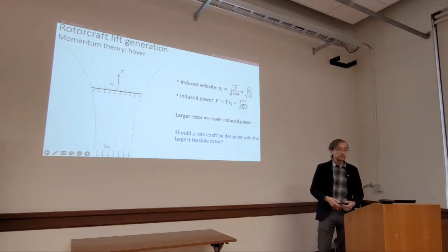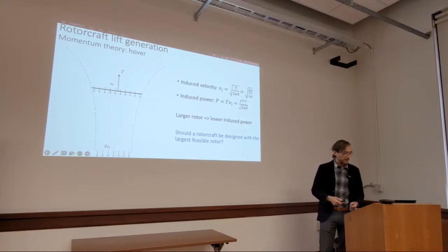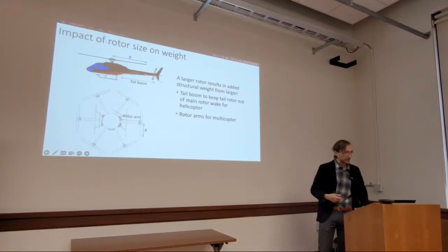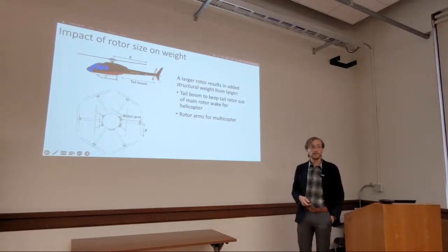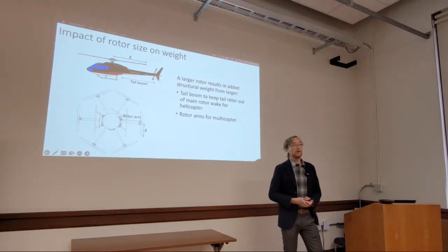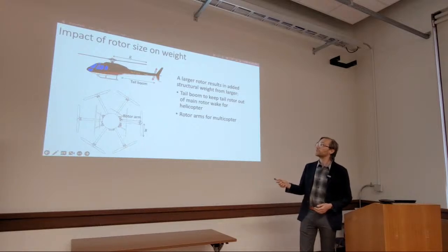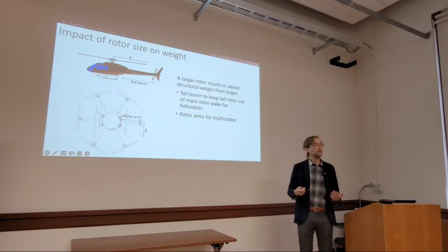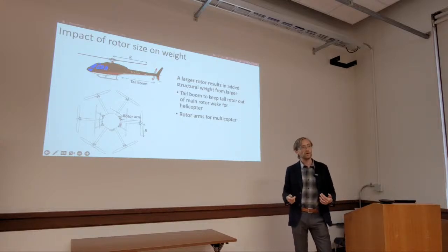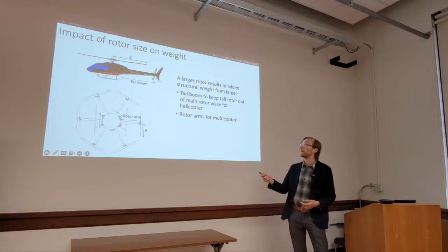Of course the answer is no, because there are some constraints and issues that come up with a large rotor. First of all, if we have a large rotor, we are going to need some added structural weight to even hold that rotor. For example, a helicopter usually has a tail rotor to create a counteracting torque that opposes the torque created by the main rotor.